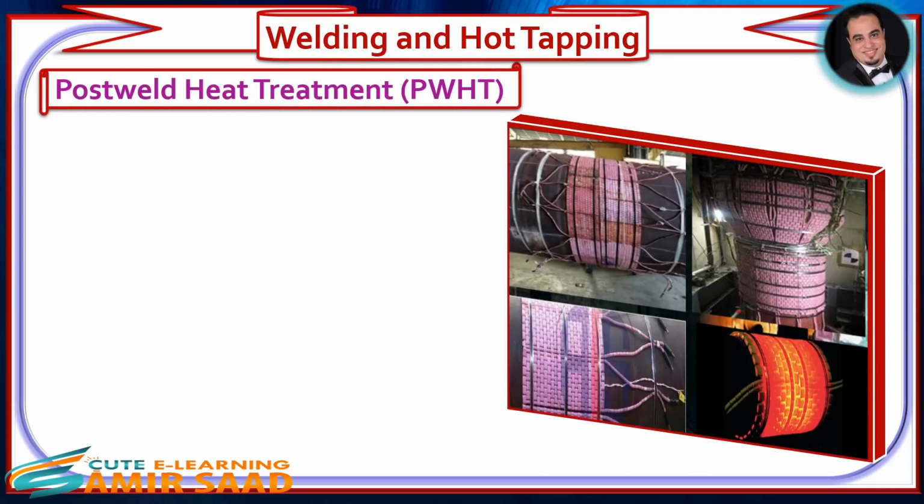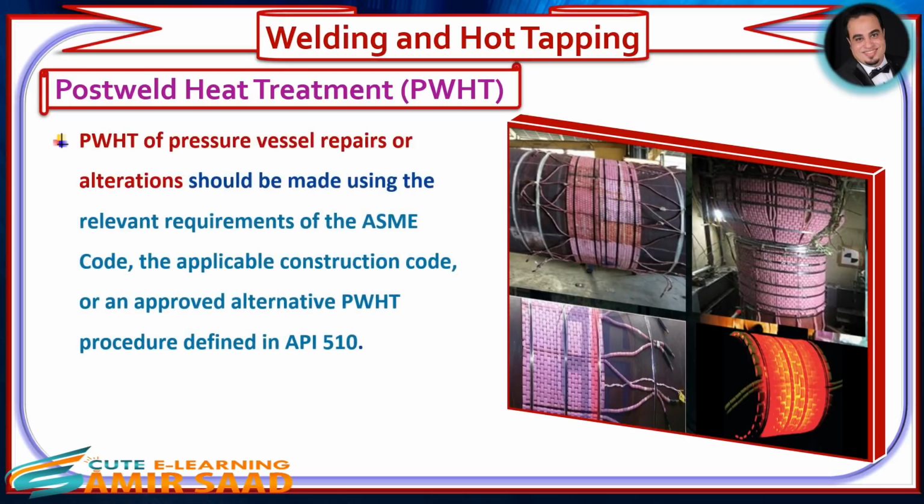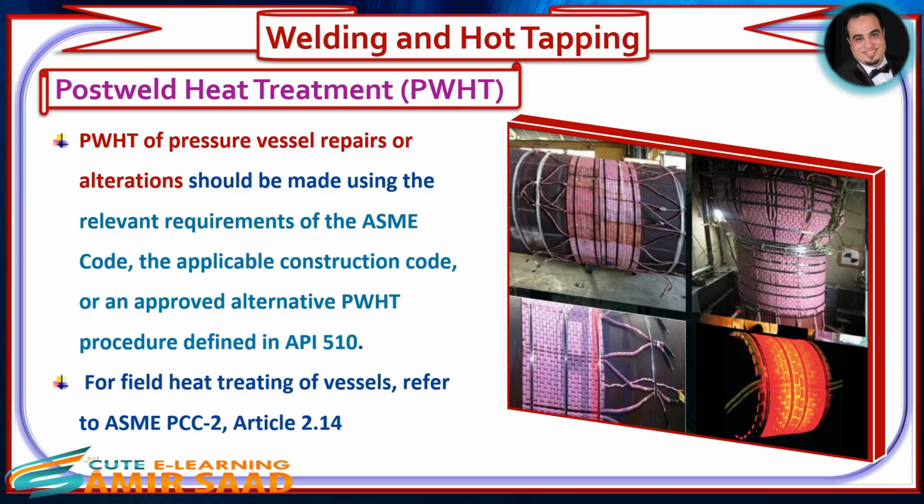Post-weld heat treatment (PWHT). PWHT of pressure vessel repairs or alterations should be made using the relevant requirements of the ASME Code, the applicable construction code, or an approved alternative PWHT procedure defined in API 510. For field heat treating of vessels, refer to ASME PCC-2, Article 2.14.